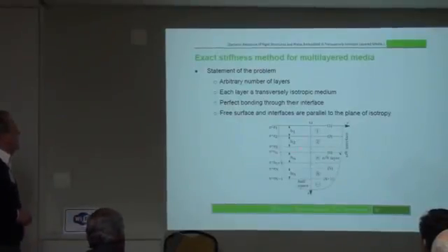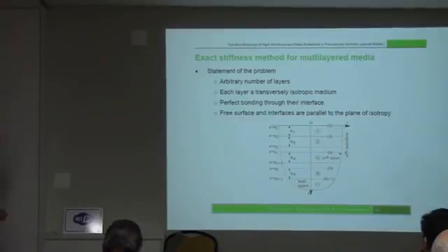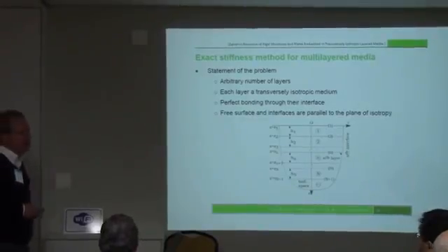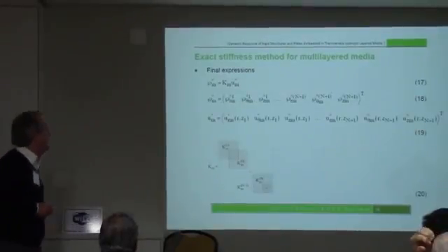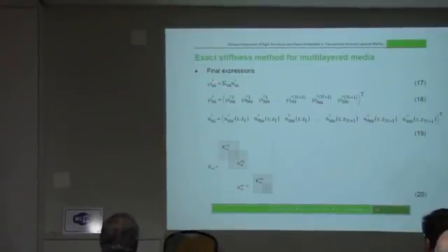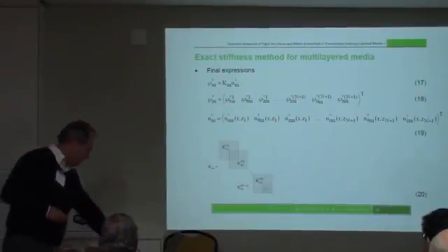To obtain the stiffness matrix for the layered media is a classical standard procedure, having the equations for the layer and imposing continuity and equilibrium at the interfaces. So this is very classical, and you come up with a finite-like system with tractions and displacements, where you have the layers, and you may have a layer or a half space here. In case you have a half space here, this is the structure of the system. We have all the degrees of freedom at the layer interfaces here.